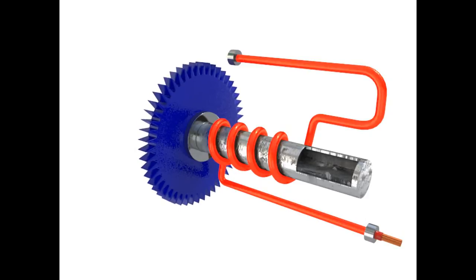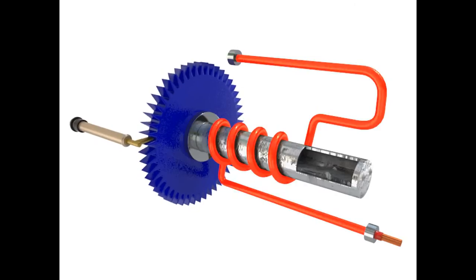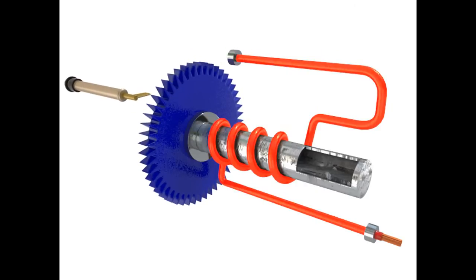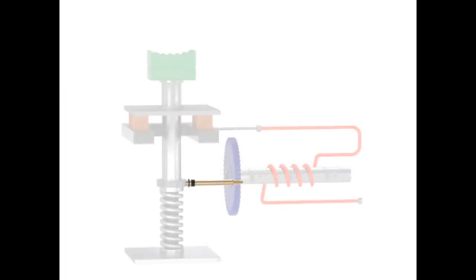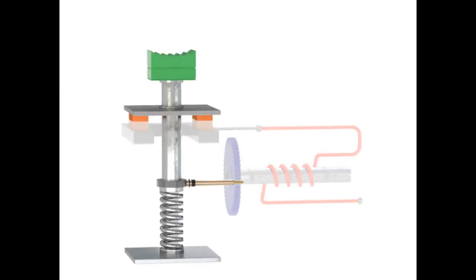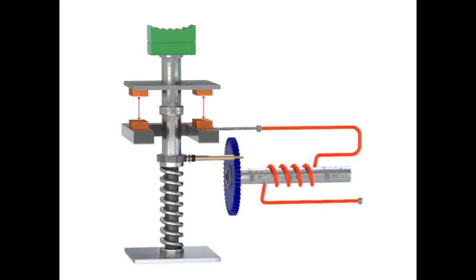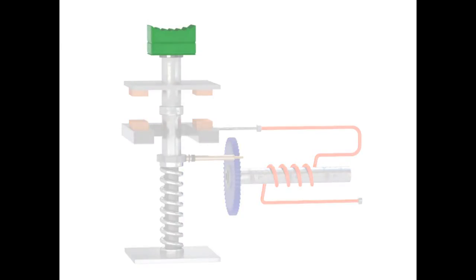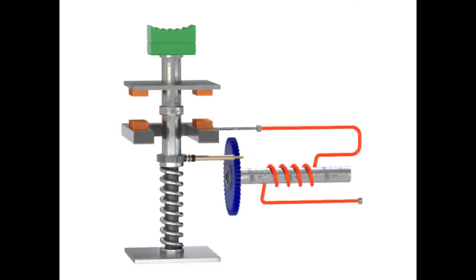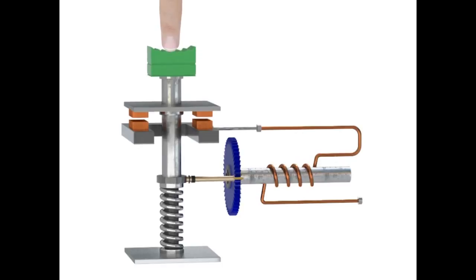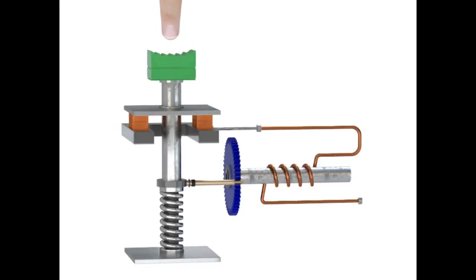When the wheel turns, it releases a pawl previously engaged in one of the cogs of the ratchet wheel. This pawl is connected to a spring-loaded contact fixture, such that when the pawl trips, the contacts automatically open and stop the current flowing to the motor starter. The spring-loaded contact fixture also includes a reset button so that when the eutectic alloy cools and cements the ratchet in place, the contacts can be closed by re-engaging the pawl in a cog and compressing the spring.